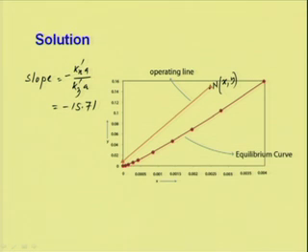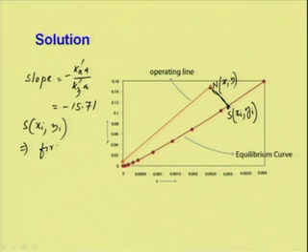From this point we plot a curve with that slope, which will meet at a point S, and at this point S you will get x_I and y_I. This is the first approximation of the interfacial concentration.